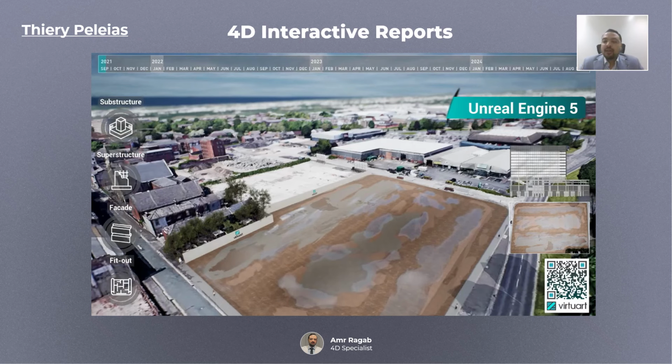Okay, you can then link it to the Unreal Engine by a plugin called iTwin Synchronizer. After that, you can directly import it in Unreal Engine, and after importing it, you need to learn some basics or some scripts in Unreal Engine. Like in Revit, we have Dynamo. The same thing in Unreal Engine, but it's called a Blueprint. Some scripts you can learn from YouTube courses.